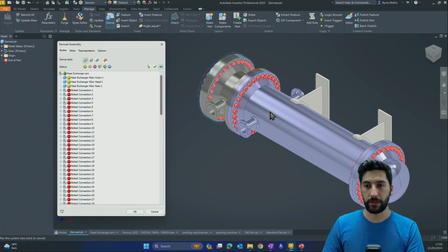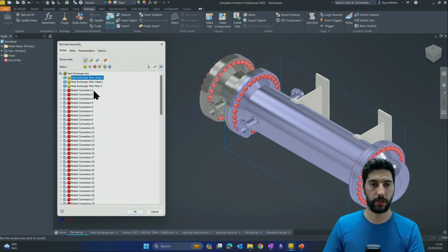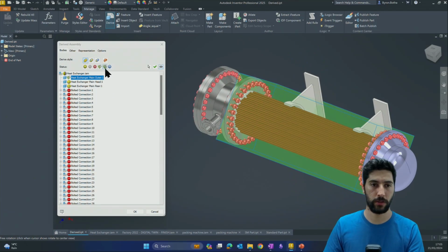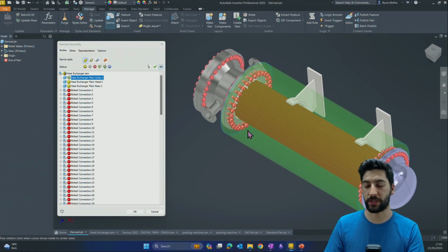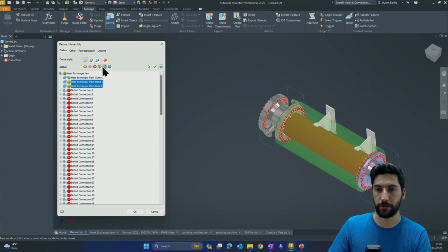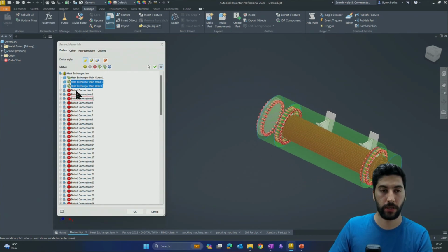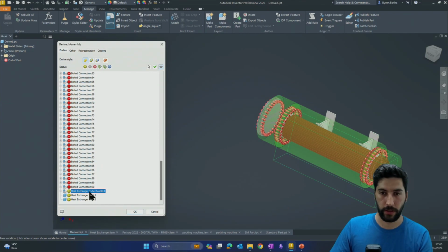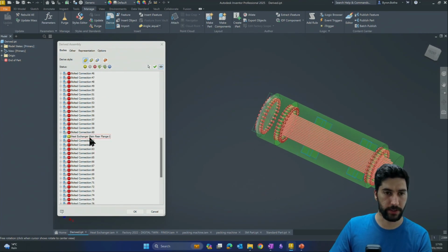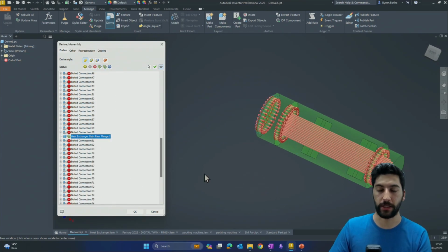And then rather than keeping this standard geometry here, I could change it to, again, rather than having that bounding square, I can have this bounding cylinder, which obviously gives me a much more realistic representation of this particular model. I'll do that to the main heads as well, and then probably just turn those internals off as well. These feet can stay square, and it looks like I just have the rear flange, and again I'll make that circular.